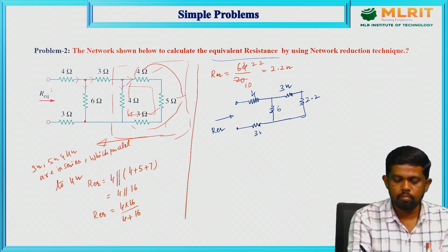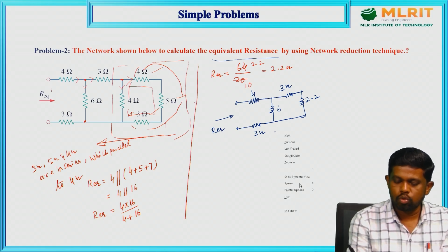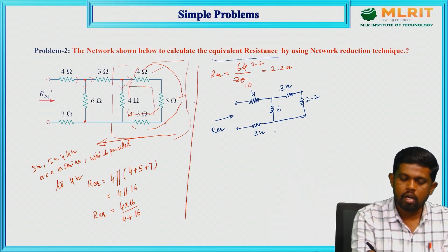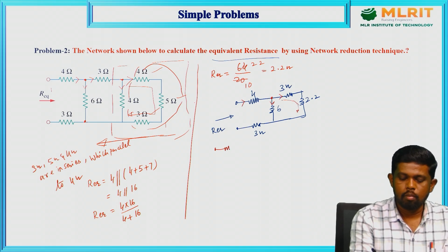This is the 3 ohm. So in this connection, we again need to assign a dummy source to identify the series and parallel combination of the elements. The current given by the dummy source is this one, so the current enters here and divides between these two. It's a simple circuit only. These two are in series and there is no current division, and that is parallel to this one. Therefore the remaining network should be like this, and we got it like this.